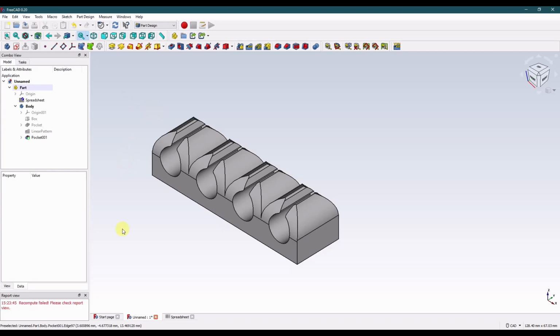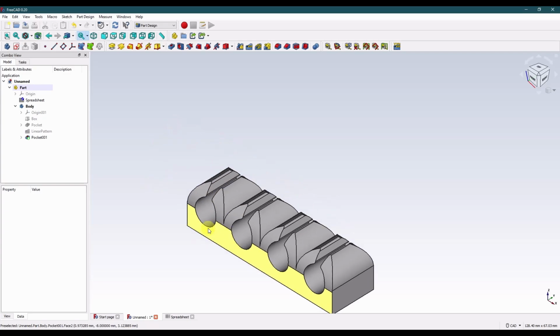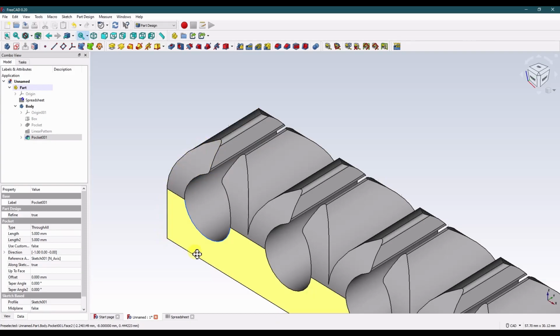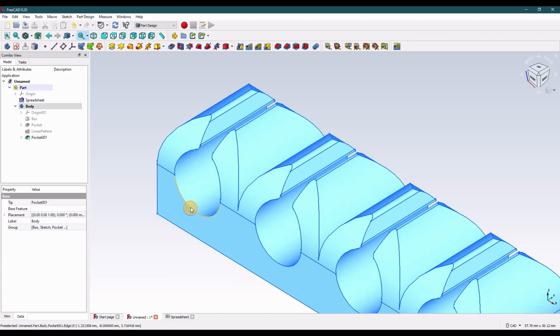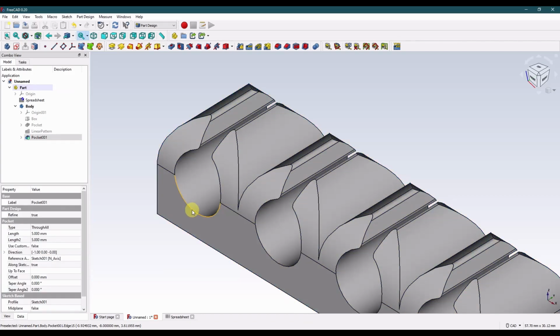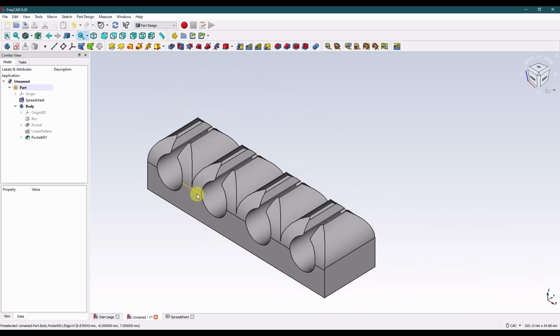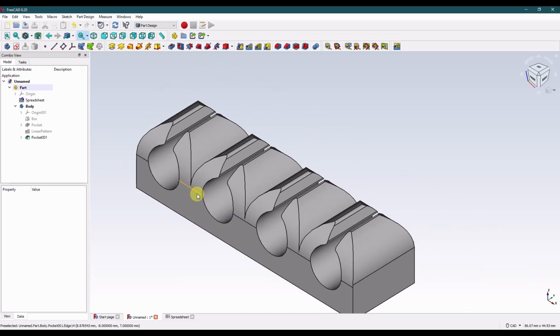Well, that's another issue with FreeCAD chamfers, is they really don't like things that are a little too complicated like this here, because really what it's looking for is it's noticing that this edge is tangent, so all of these are tangent. So technically if I was in SolidWorks and I click this edge and I try to chamfer it, it would try to do all of this. Okay, and it's mathematically tricky to do that, if not impossible.